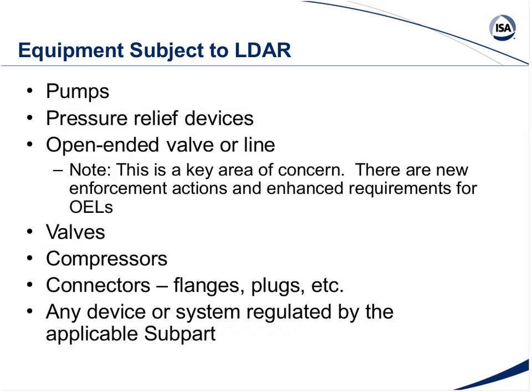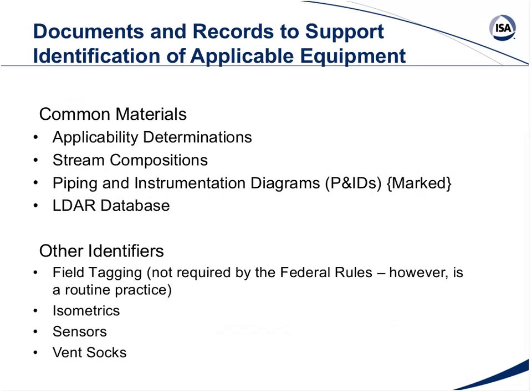And so now we have to go back and do that monitoring. So we're seeing a lot more enhanced LDAR programs that are having to include all those potential termination points as an open-ended line inspection. So you might want to look at how that's being handled at your facility.